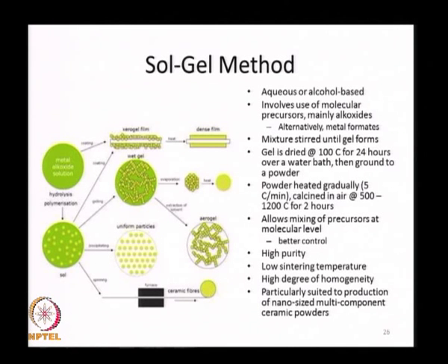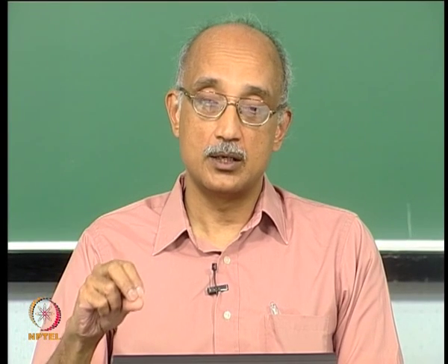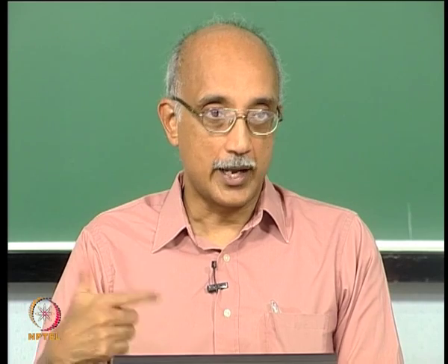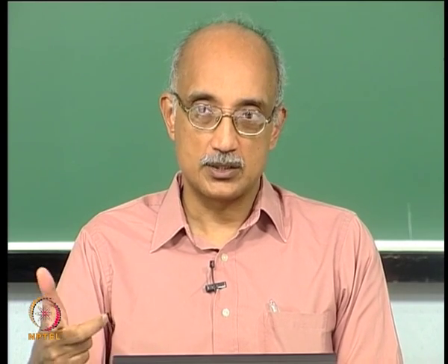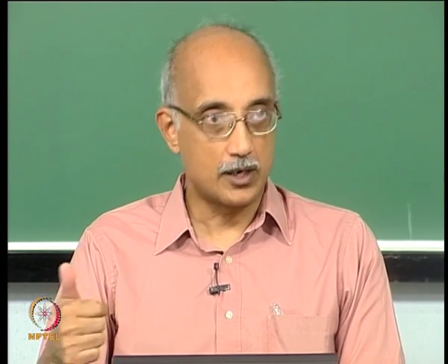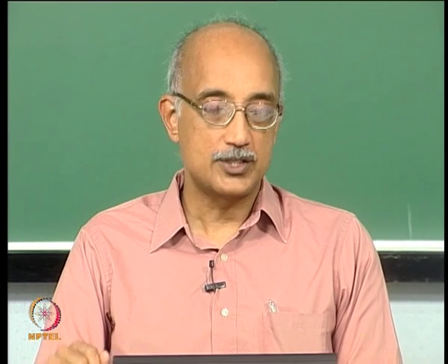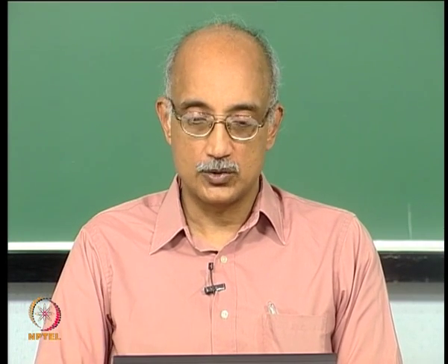The reason for that is twofold. Multi-component because you can take many different precursors in liquid form, mix them to form a gel and then grind them down. Ceramic is particularly advantageous because this top down approach of grinding to achieve a final size works particularly well for materials that are hard and brittle, and ceramics satisfy both requirements. They are hard as well as brittle, so it makes it very easy to grind them down to a certain size.